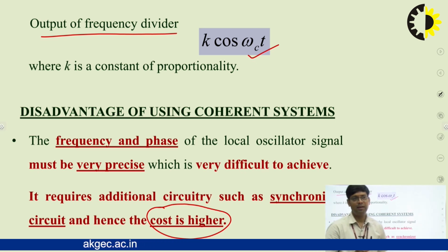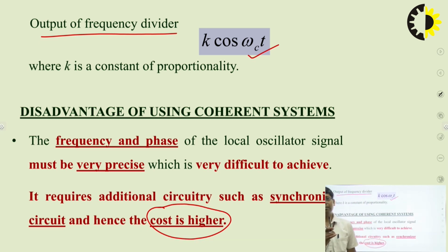So as we know, we have discussed that the advantage of DSBSC technique is that the power consumed by the transmitter to transmit a signal is less. We save minimum 2/3 of the power if we suppress the carrier at the transmitter end. That is a saving at the transmitter end. We save 2/3 of the power minimum. But at the receiver end, the drawback is the cost of the receiver circuit goes high. So this is the trade-off.